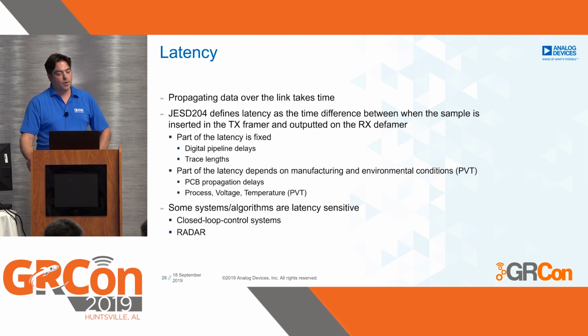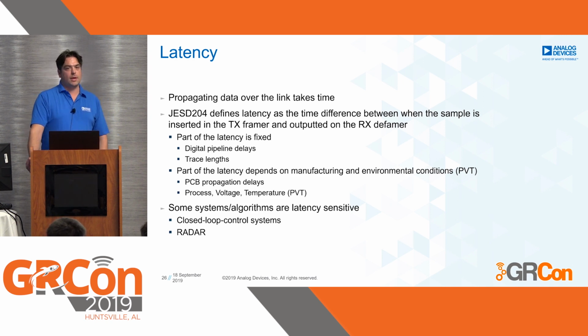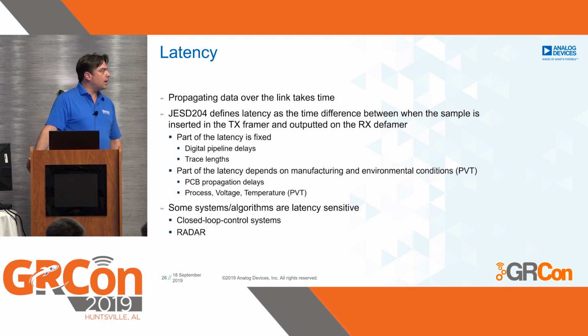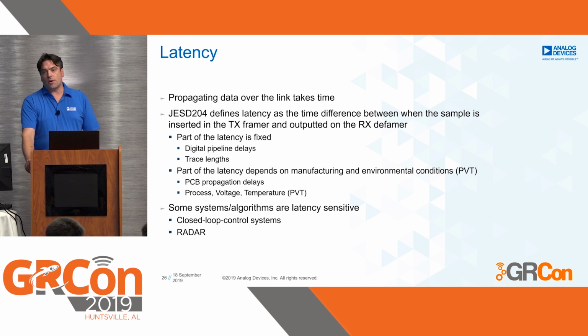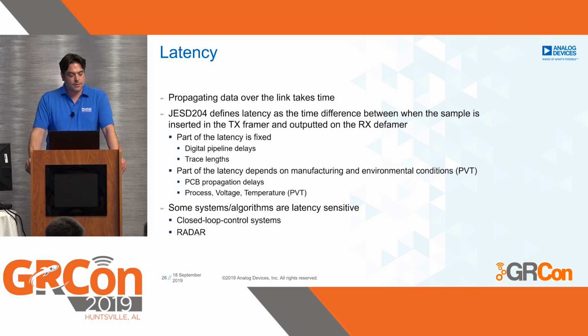So latency. Propagation over the data link takes time. JESD defines the latency as the time difference between when the sample is inserted in the TX framer and outputted by the RX framer. Part of this latency is fixed: digital pipeline delays and trace lengths. Part of it depends on manufacturing and environmental conditions such as process, voltage, temperature, and also PCB propagation delays. A lot of systems are latency sensitive, so all closed loop control systems, and of course also radar is one of those systems.